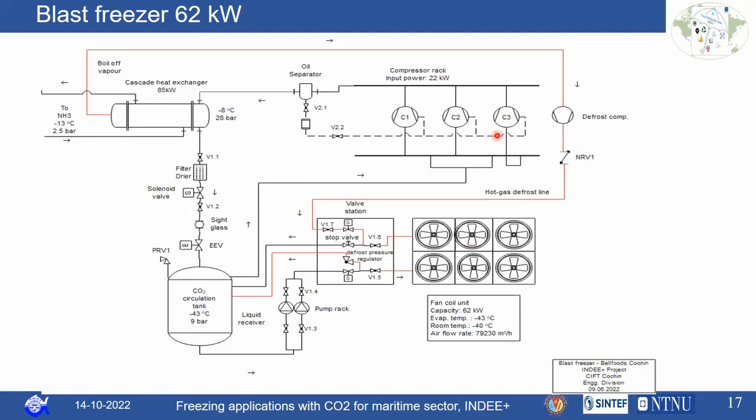So in the case of the blast freezer, as I said, the blast freezer goes through a batch process. In the batch process, you load the fish for about 4 hours. Your full time will be 4 hours. Then after the 4 hours, you go for the next batch of fish. So in between that, if the moisture content of the fish is high, you have to go for the method called the defrosting method.